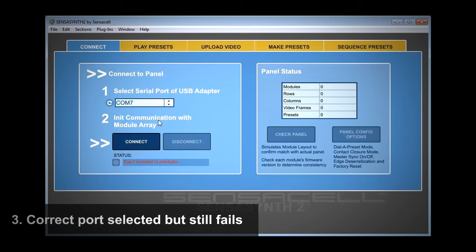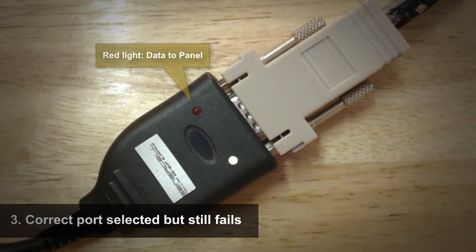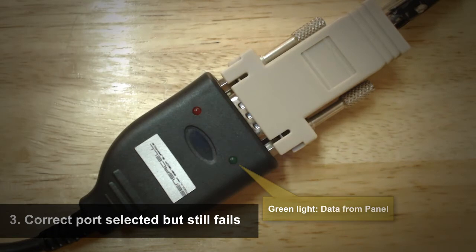A further confirmation that you have the correct USB port and that the adapter is working correctly can be had by watching the small LED lights on the USB adapter. If the red light flashes when you click the Connect button, the adapter is sending data. It is receiving data from the Sensacell panel when the green light flashes.